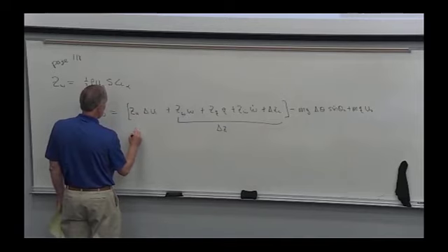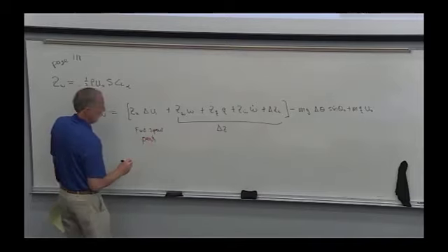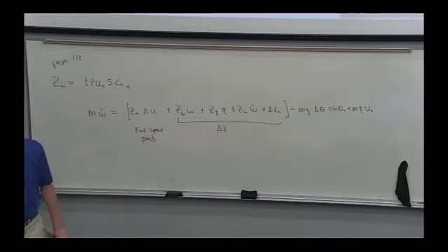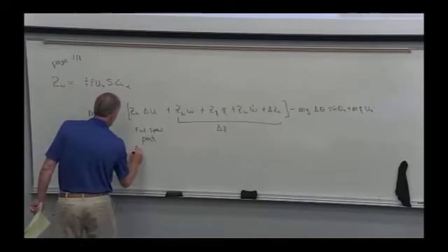So it turns out that forward speed perturbations can be important when you're flying close to Mach 1. Because when you're really close to Mach 1, a small change in airspeed changes the shockwave pattern on the wing and the fuselage. So this is really a Mach number effect.